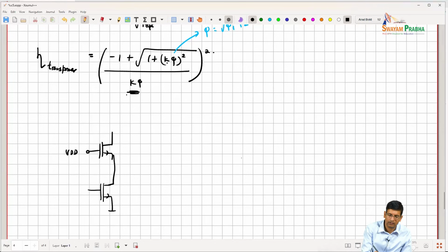And then this node voltage is VDD on the cascode, right? So you can design this with a larger swing, because you can accommodate some larger voltage here.